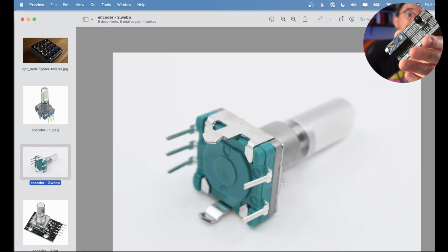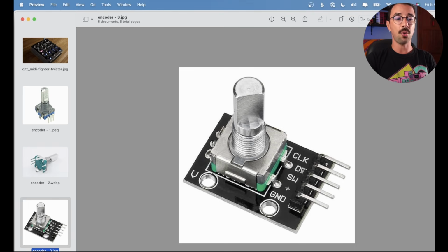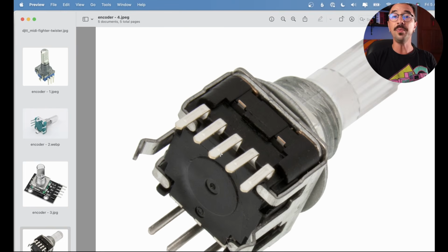just like any regular button. You can see those encoders also on a breakout board. So it has the pins here, also the encoder plus the switch. And you can also have illuminated encoders. So this one has built-in LEDs. It can be 1 LED, 2 LEDs, or even 3 LEDs, an RGB LED. So you can have all the colors. So it will have more pins, so you need to be careful to read the datasheet and understand which pin is which.